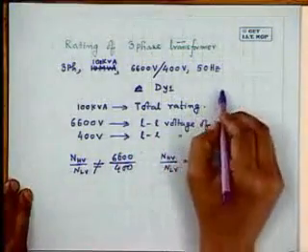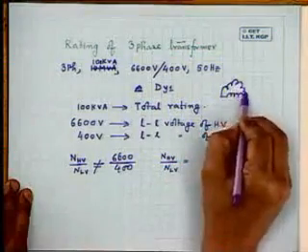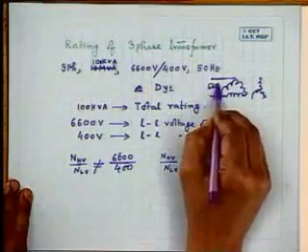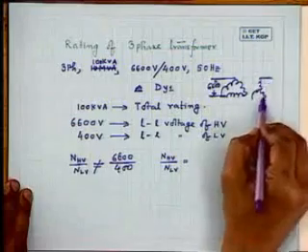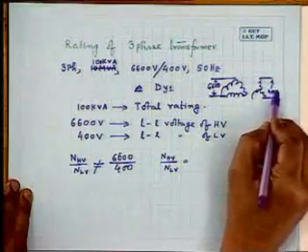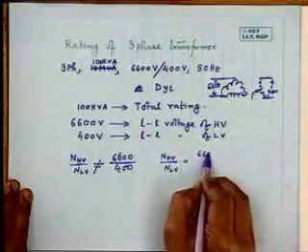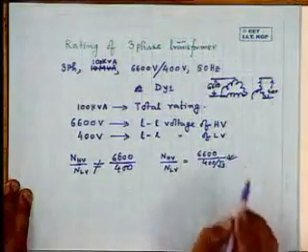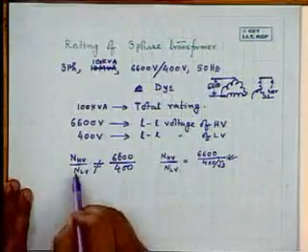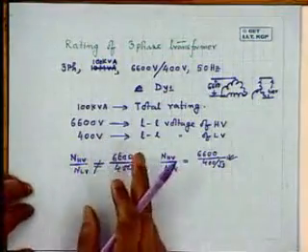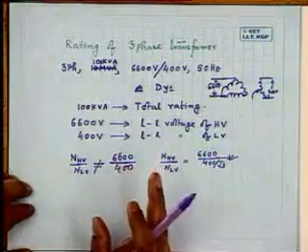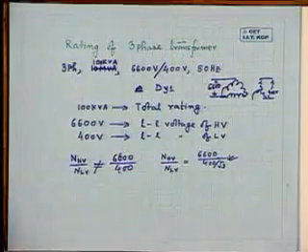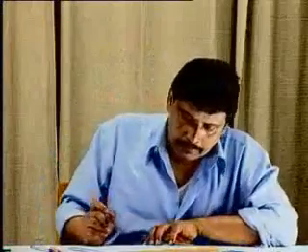The voltage applied line to line voltage, that is this connection is just a simple diagram, delta, this side star. So this voltage we are telling it is 6600 volt, 6600 volt, and this side it is 400 volt. So it will be 6600 divided by 400 by root 3. That you should be very careful about. So turns ratio may not be equal to the voltage ratio, line to line voltage ratio. Of course it will be, provided the connection is delta delta or star star. In that case there will be no distinction.